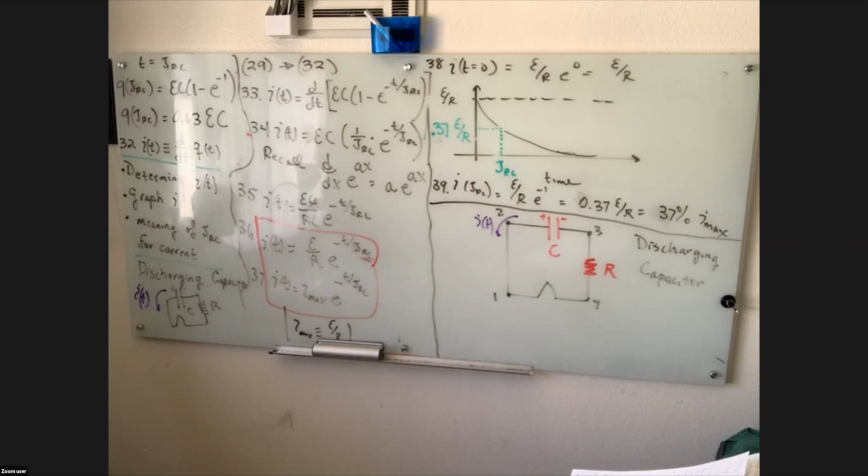When I ask you how much voltage will be dropped across that resistor, I want the answer in terms of the I of t, the R, and the nature of whether the voltage will increase or decrease for a charge going through that resistor as you traverse it in the orientation that we are keeping, which is the counterclockwise orientation.